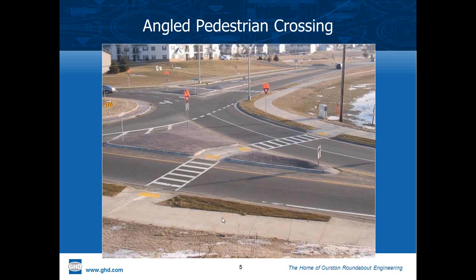In North America, we're accustomed to installing roundabouts, and where there's a reasonable chance of pedestrian activity, we locate the roundabout crosswalk approximately one vehicle back, or roughly 20 to 25 feet behind the give-way line or the yield line. And it's usually the physical bullnose of the median that is the point where we measure back from where the vehicle would line up. And so it allows for one vehicle queue space between the give-way point and the crosswalk.